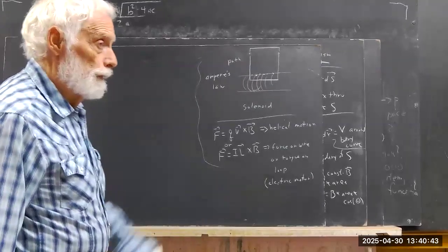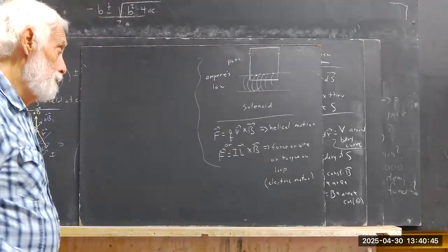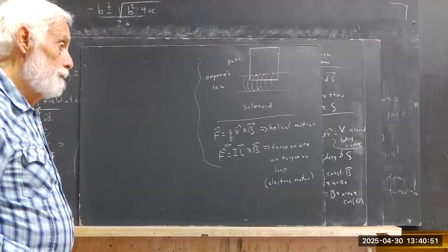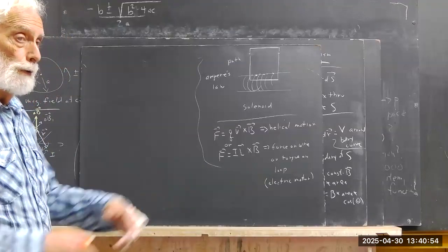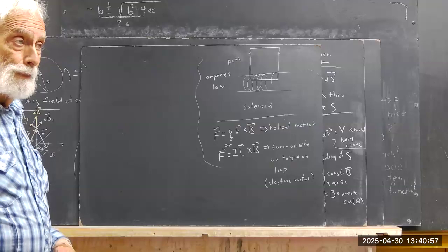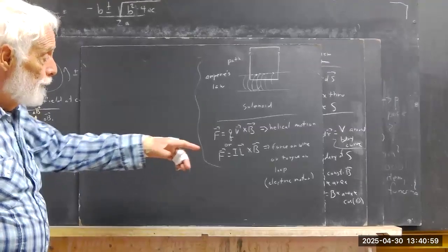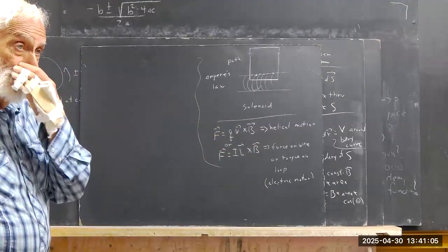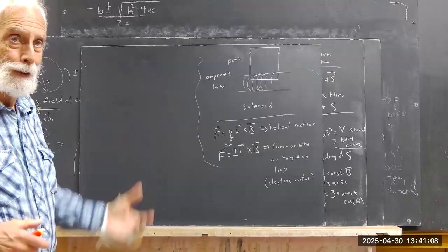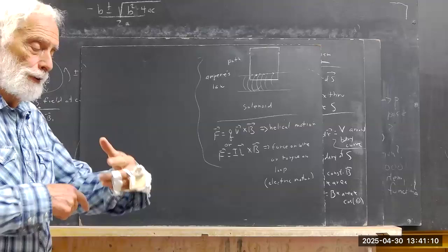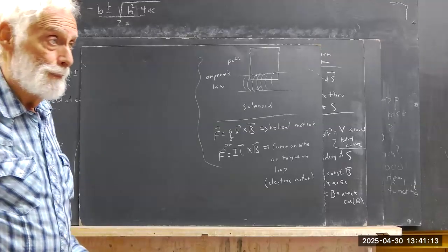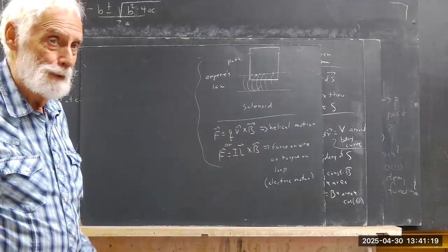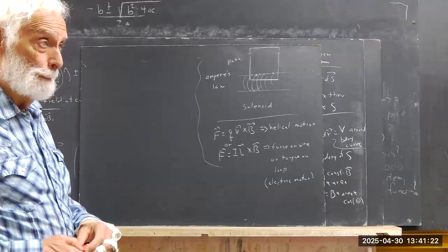But when I look at even the idea of an electric motor, where you've got a loop and you've got an alternating current, you use that alternating current in the loop to react to the magnetic field. And use a commutator to reverse the direction of the force as the loop passes 180 degrees and all that stuff. I'm not going to give you a test. I'm not going to ask you to design this thing, but you want to understand those concepts.